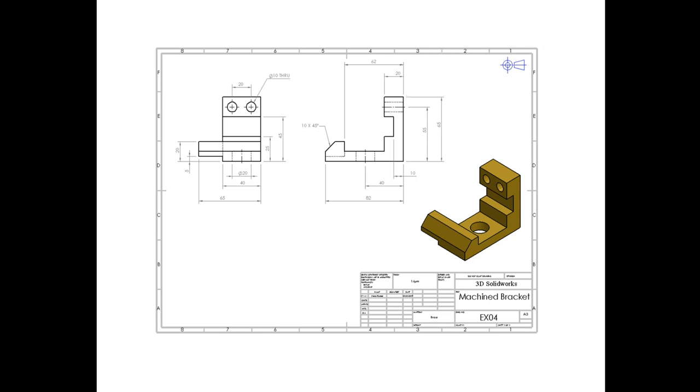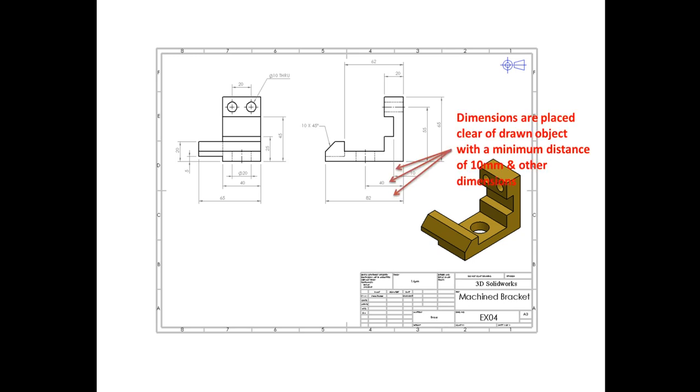And finally, the way in which you lay out and position things clear of an object. Don't cramp dimensions. Like I said earlier, don't over dimension. Just put sufficient dimensions on. We need to leave 10 to 15 millimeters between the dimensions. Cramped dimensions are difficult to read, going to lead to long-term problems where we're going to get mistakes made and drawings not working for us. So we're going to look at how we import the dimensions and how we set up drawings and the drawing setup within